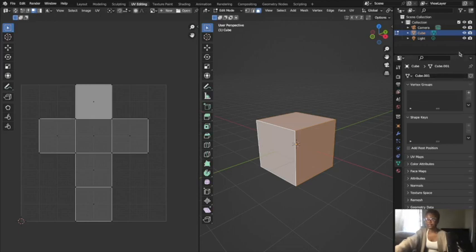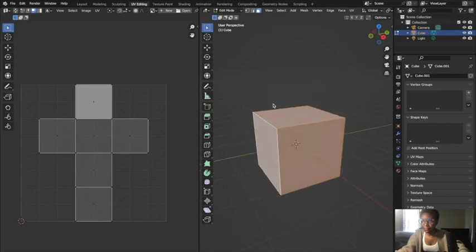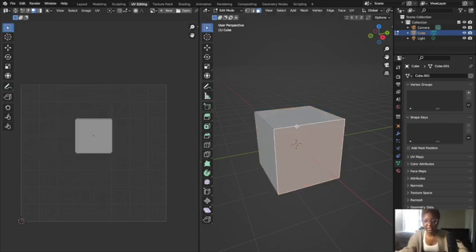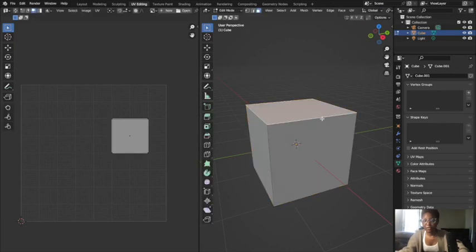Now, as I mentioned before, UV meshes are not created with UVs automatically. Sometimes Blender will automatically create default UVs, but these UVs are still not mapped. They may not be mapped accordingly to what your mesh looks like, so you can always edit these UVs. To do that, the process is called unwrapping your model. So of course, we'll go into edit mode to select the mesh, and again, this will allow us to edit UVs. To begin, we're going to choose again the UV editing workspace, which is where we are.